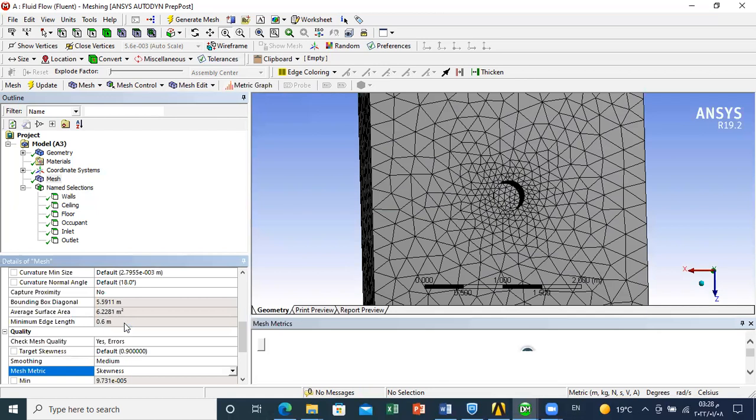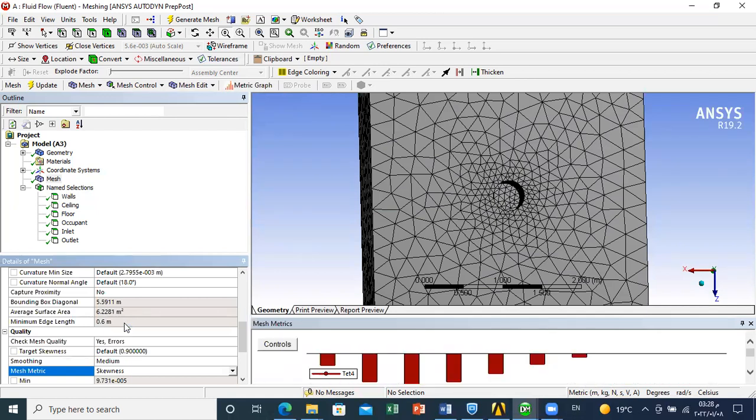So first, concerning the skewness, what does skewness mean? The skewness of a grid is an indicator of the mesh quality and suitability. The larger the skewness, the worse: it's not good to have very large values of skewness, because large skewness compromises the accuracy of the interpolated regions. We can define skewness as the difference between the shape of the cell and the shape of an equilateral cell of equivalent volume.